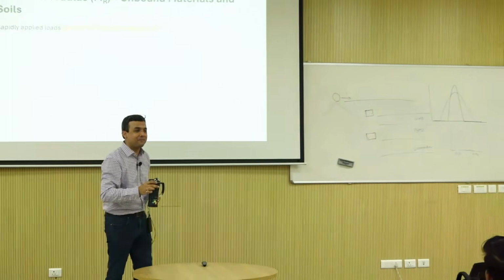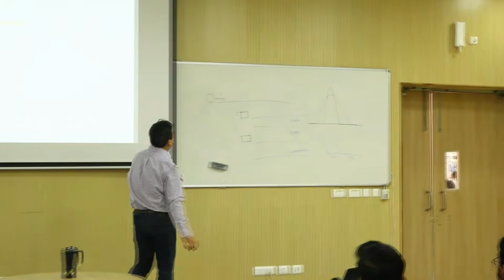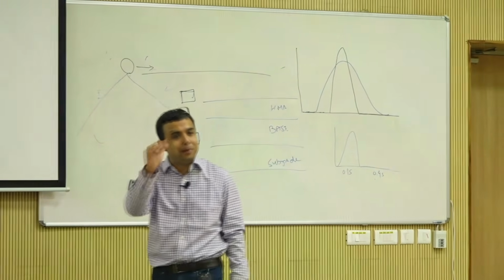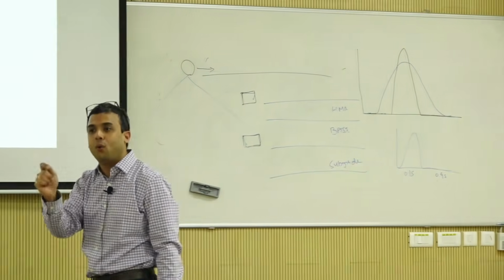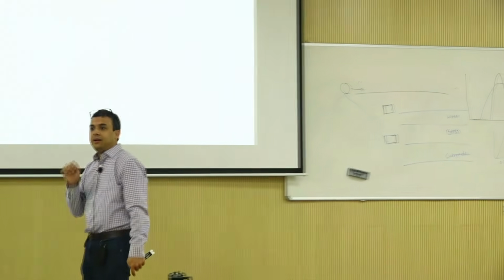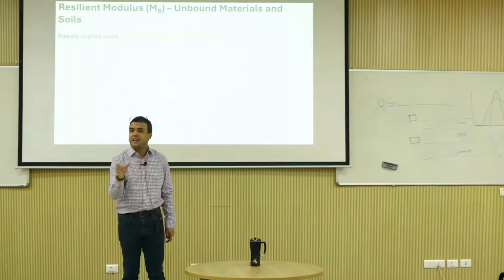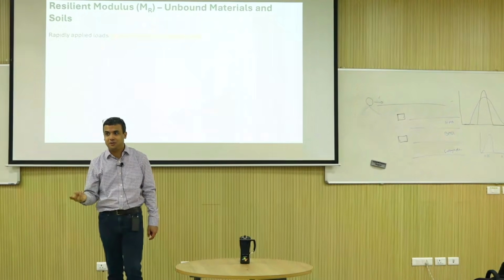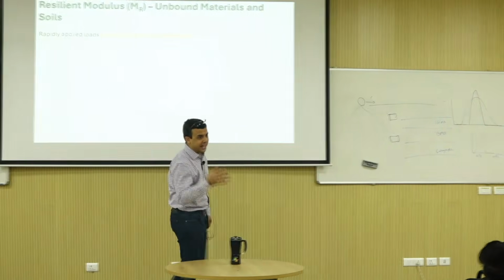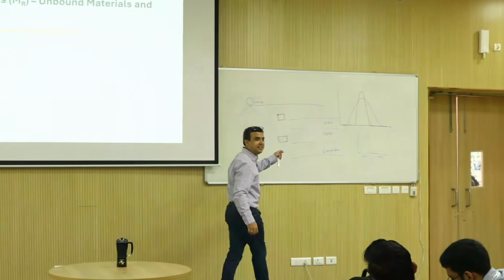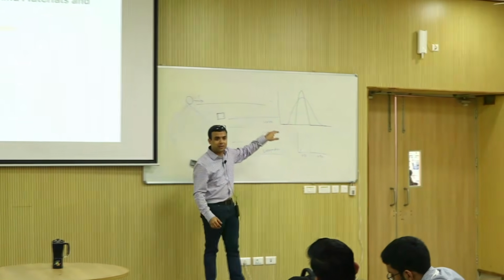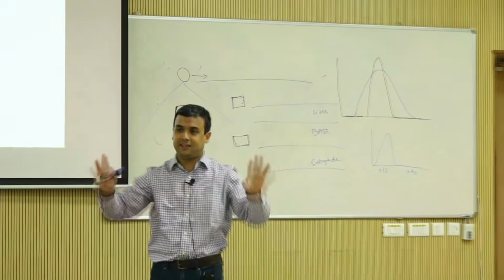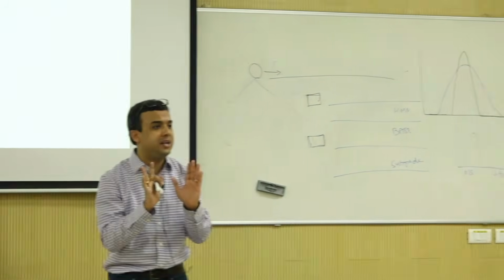So the point is, if you actually go and track the rest period and the pulse width, it should change depending on where you are in the layer. If you look at the code, for the subgrade, yes, it is acceptable to do it at 0.1, but it's actually also recommended to do at 0.2 and 0.8 in AASHTO T307. Whereas aggregates are usually 0.1 and 0.9. That's the reason, because they are above the subgrade and the pulses are going to be a little narrower. And the stress states are different for sure. That we all know, we all agree. So the width is going to be different.